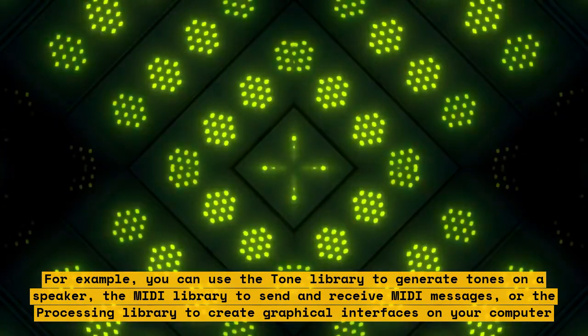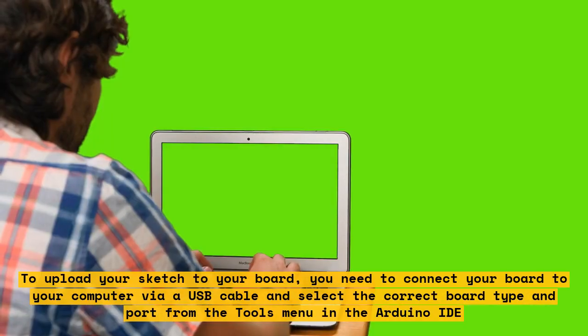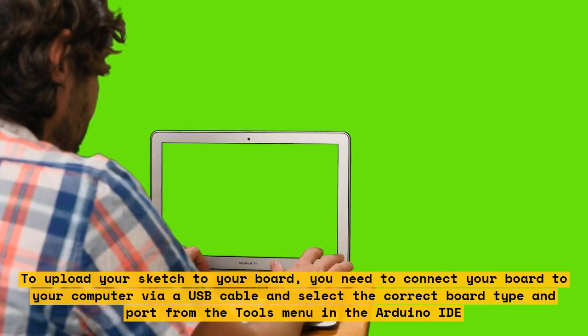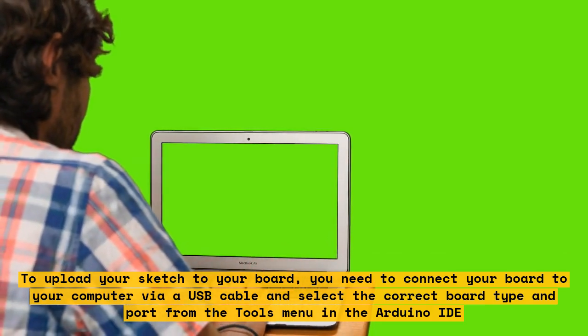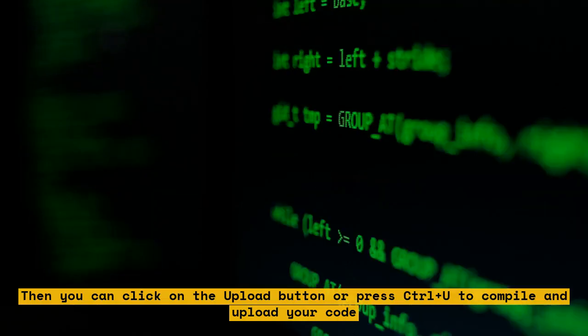To upload your sketch to your board, you need to connect your board to your computer via a USB cable and select the correct board type and port from the Tools menu in the Arduino IDE. Then you can click on the Upload button or press Ctrl+U to compile and upload your code.